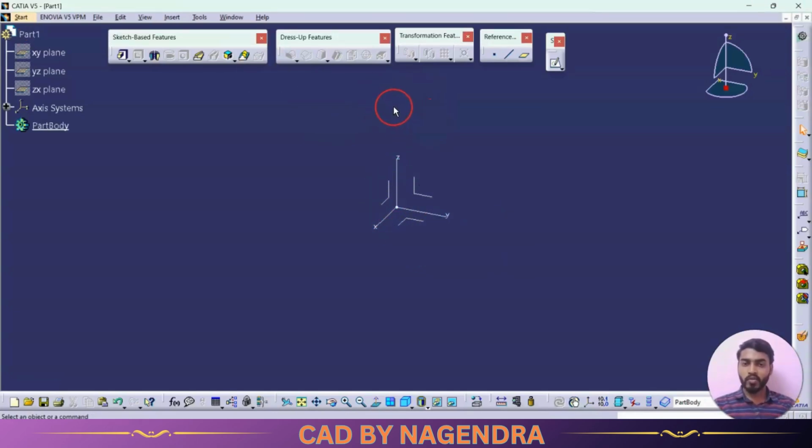Now let's say for example on base we are having one shape, and with some height we are having one more shape. So if you want to create any profile at some distance, directly we are not able to create on this empty space. So here we use help of reference elements. In reference elements we'll be having point, line, and plane.